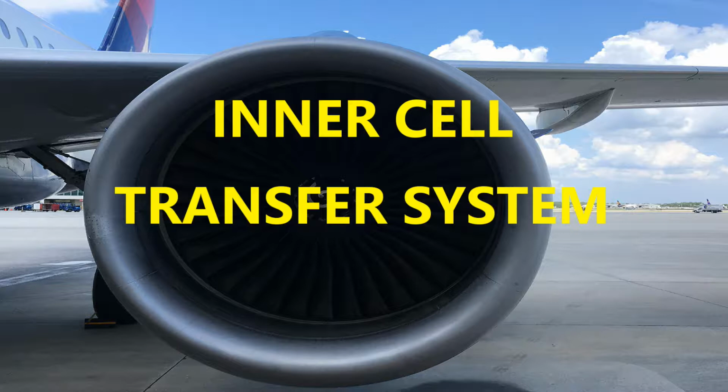Just so you know, the intercell transfer system is controlled automatically by the computer. Like I said, if it reaches a certain low level, the valves are going to open. And they're just going to continue to stay open until the next time the plane gets refueled. So that's what you have with those intercell transfer valves.